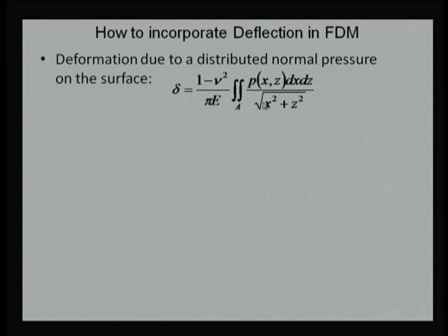It is nothing like individual molecules or individual pieces that will simply deform under the load. Here we need to incorporate a combined load, and that is what we are trying to convey. This is the deformation which we did in the earlier case, in a previous slide, in polar coordinates. Here we are writing it in rectangular coordinates, because the pressure we expressed in hydrodynamic lubrication was in terms of x and z. So, there is an area dx into dz, and this is the main thing.